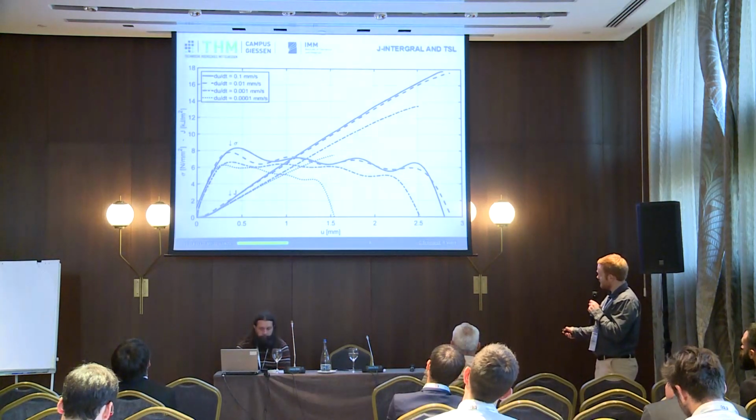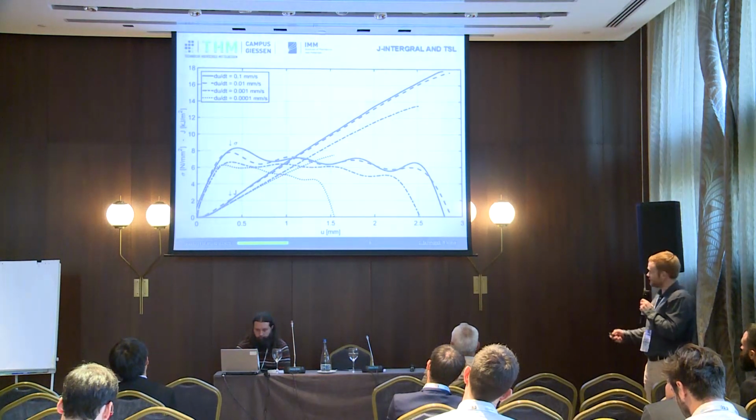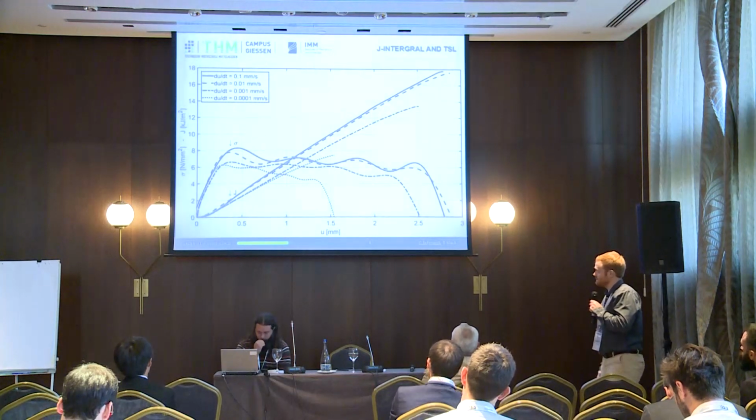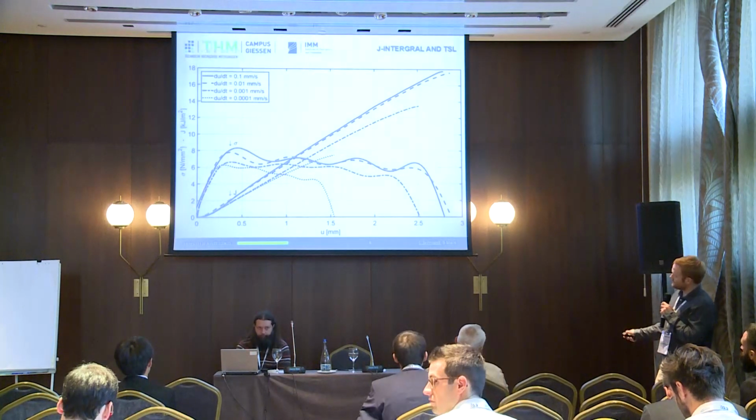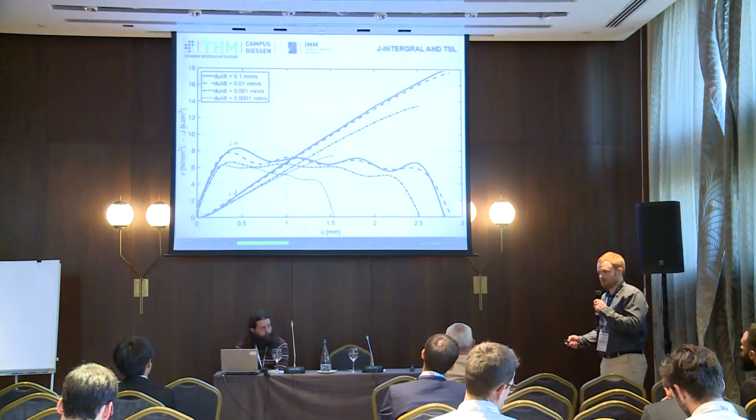But the cohesive strength, as the plateau stress, is rising as well as the fracture energy. So two of the cohesive law parameters are dependent on rate, and stiffness seems to be not dependent, although we have viscoelastic material behavior.